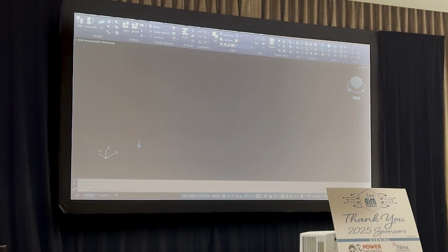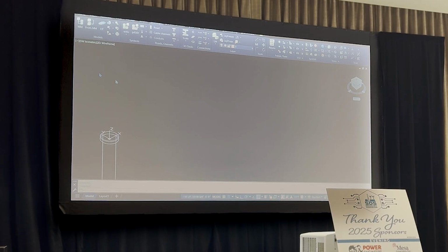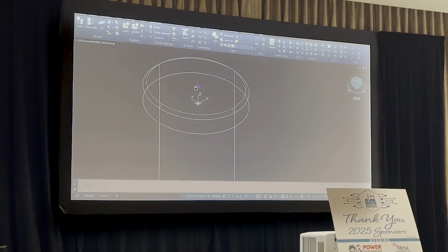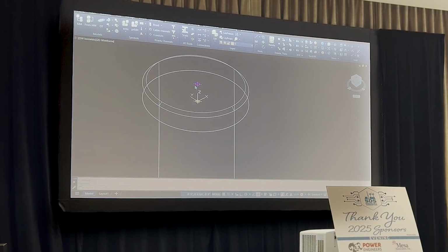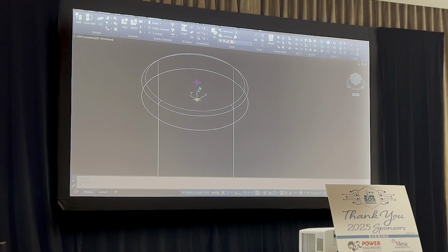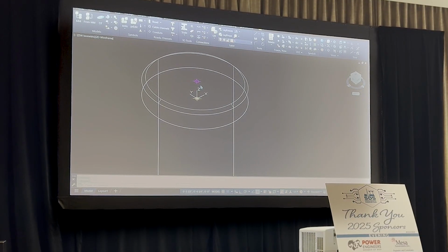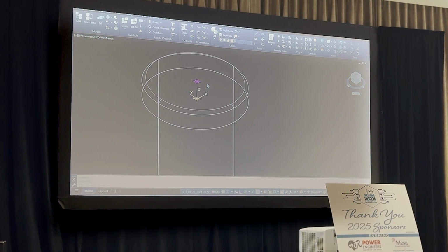And I'm going to kind of explain some things as I zoom in here. So, to place this, since I'm in AutoCAD, I know I'm going to center it on the origin. I can type 0, 0, and place it to origin, and it's going to snap over here. And then if you look at this one, you'll see these points, these pink and yellow points. These are nodes, and they're used for connection. They have no other intelligence besides where you place them. The color is strictly visual, right? Yellow ones are what I use for origins most of the time. Pink ones are connections, right? So that's how I place that foundation.